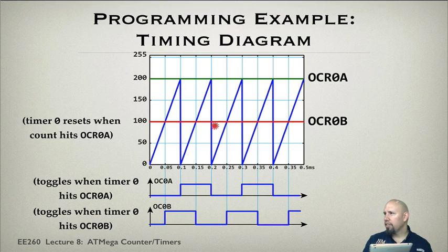So it climbs up, this signal goes up and comes down when it hits it again. Notice even though it drops here, it doesn't actually hit that value. It actually jumps from 255 down to 0, so it completely misses that value. But it continues on, and it'll eventually hit here. So it'll hit here, here, here. It's always hitting when it's climbing. And each time it will toggle.